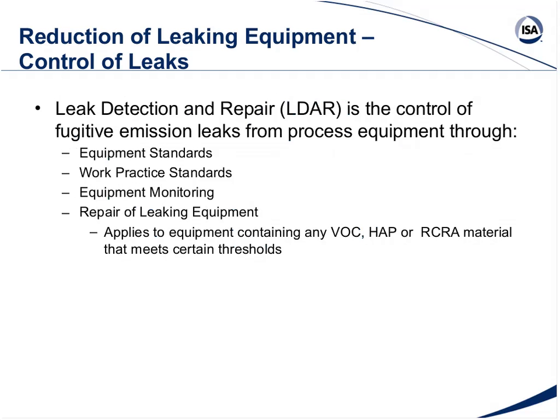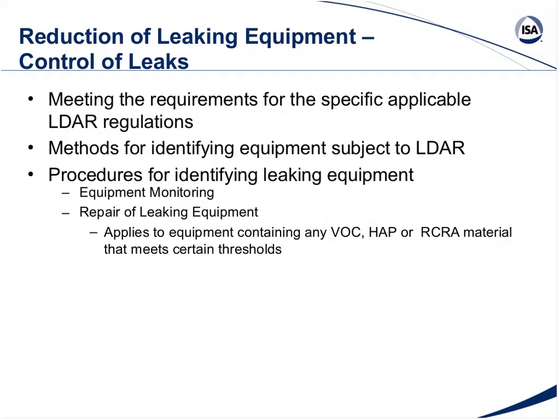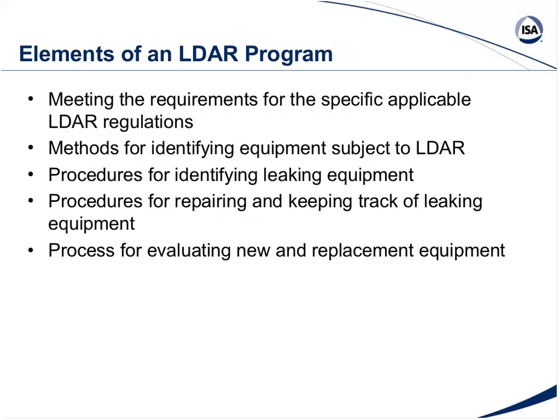So we deal with our process equipment through equipment standards, as I've already mentioned. We deal with them through our work practice standard, and we're going to walk through this work practice standard, and then our equipment monitoring. If we find and detect a leak, we've got to do something about it. We have got to repair that leak, and we've got to make sure that that leak gets repaired in a timely fashion. So let's look at the specific elements of an LDAR program.